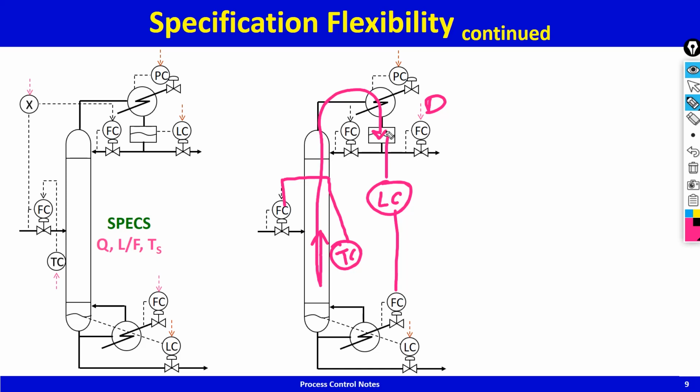So the vapor reaches the top in a few seconds, so that will immediately reflect in the column pressure, and then the column pressure controller will crank up the condenser duty and the condensate rate will increase, and that will cause the reflux drum to fill up. Of course, the action of this level controller is nested with the pressure controller.